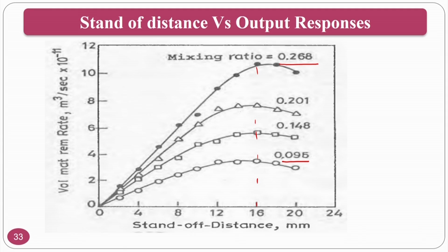If the stand-off distance is too small, what will happen? It does not have sufficient velocity to carry. So, you also need the stand-off distance at an optimum value, so that you can hit the workpiece.